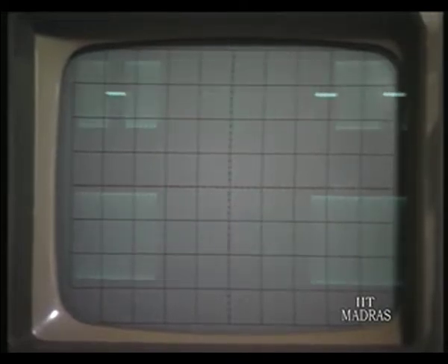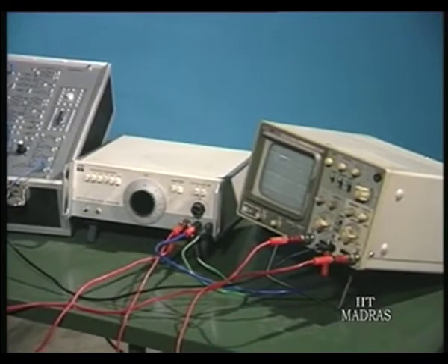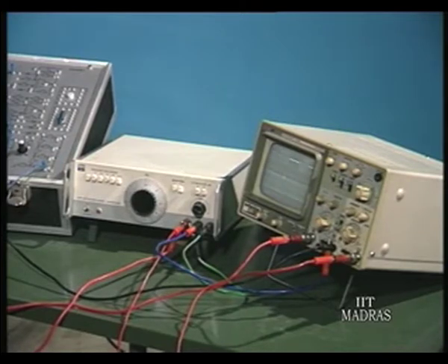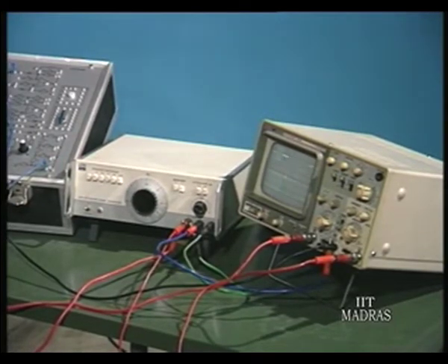It is the modulated output. Please vary the modulating frequency now from 100 to 50 or something. So, she has changed the modulating frequency from 100 to 50 hertz, and now you can see again the modulated output. See, the frequency is different. So, gain is made very nearly equal to 0, nothing of the output is visible there, and output is fully visible during the other interval. So, it is a square wave modulation. Okay. So, this is a clear application of multiplier.